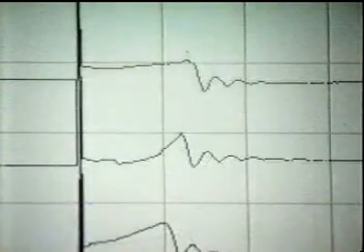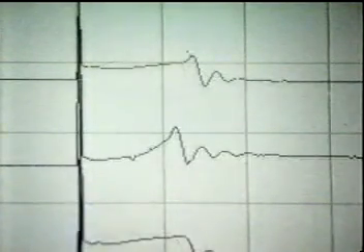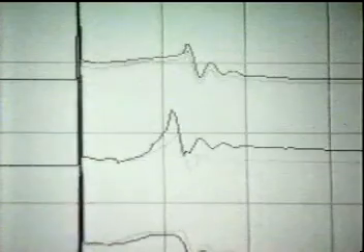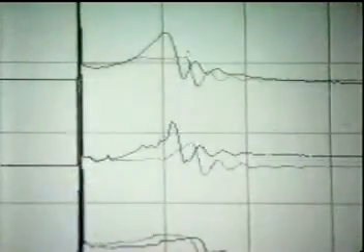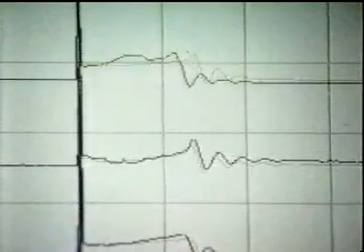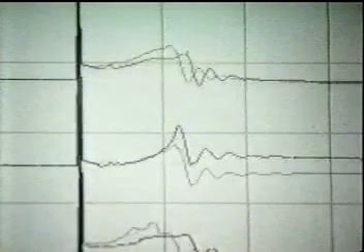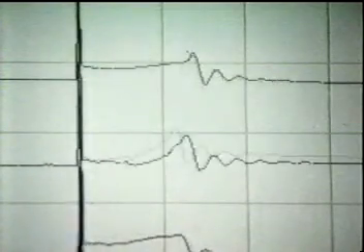Notice that cylinder number 3 spark line seems to be slightly shorter than the rest of them. Now, if you recall during the presentation, we told you a GM Type 2 coil pack will maintain a typically 1 to 1.2 millisecond burn time. The scope is right now set on 1 millisecond per division. However, if you focus on number 3 cylinder spark line, you can see it consistently dips below the 1 millisecond burn time. We are suspecting a lean hole from an injector that's stuck shut.